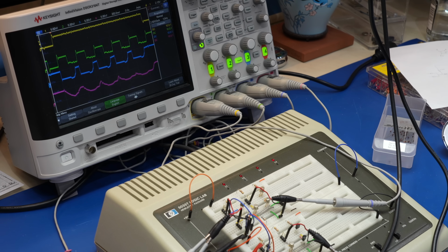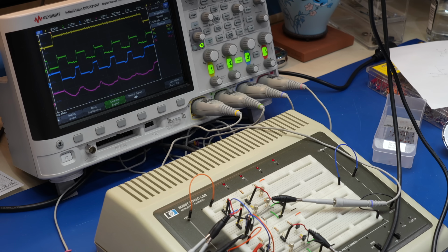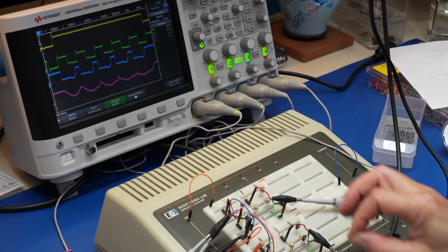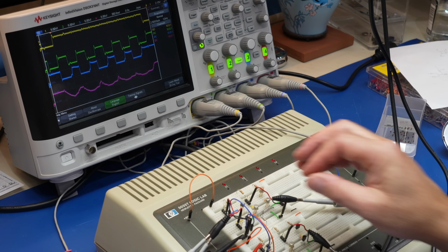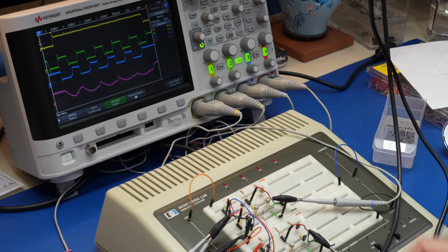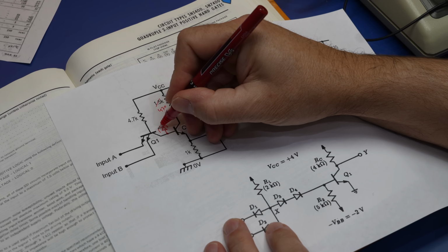Let me demonstrate. I had a Schottky diode somewhere. Here it is. So a Schottky diode, this little guy, a diode that's A, very fast, and B, has a very low voltage drop across it, 0.2 volts instead of 0.6 volt for a silicon diode. I put it between the base and the collector and look at what happened. Now my transistor is way faster getting out of saturation. And the reason is that the diode prevents the transistor from going too deep into saturation. It has only 0.2 volts.